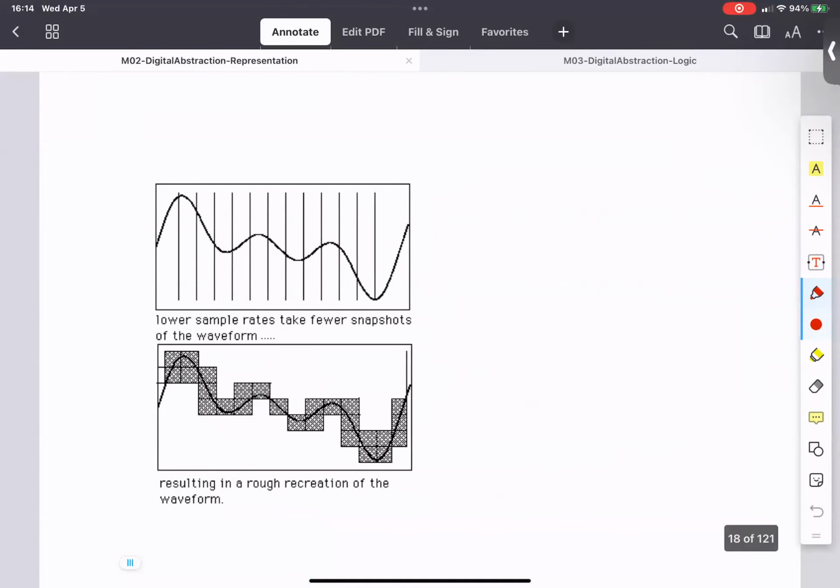So conceptually, what's happening is I have this waveform, this guy, and I want to convert it into discrete values. When I'm converting to discrete values, I also have to discretize time, because I'm going to deal with just a set of values, different values for different time instants. And the values themselves also need to be discretized. So I have to have some strategy for deciding at what instant in time I measure the value. And then the other thing is, once I measure the value, I need to map it into a certain finite number of bins.